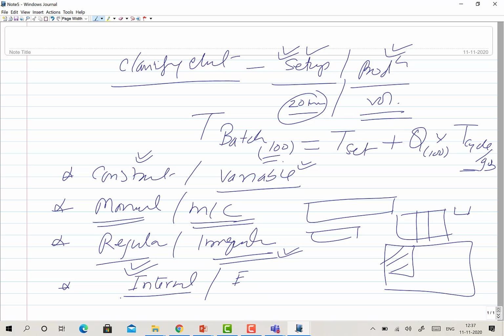So the time consumed in internal elements may not be added to the time required to complete the job. But when certain elements are performed in series, like hold the job, then perform turning, then unhold the job, these three are in series. So this is an external element. Internal elements are those which are performed in parallel to some other element or job when it is being done, and external elements are those which are performed in series.